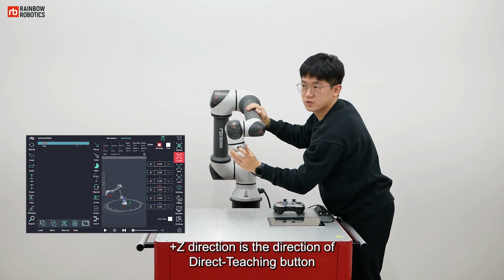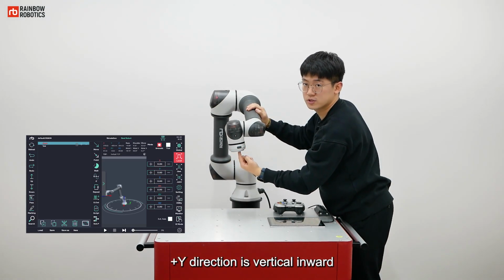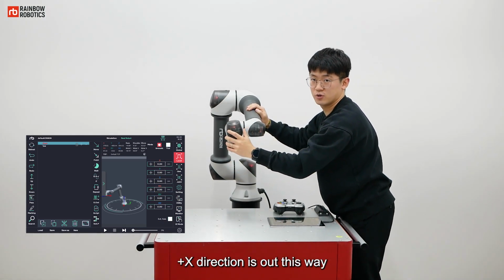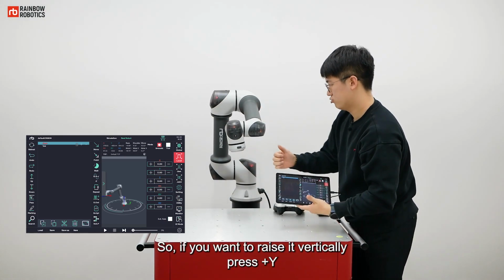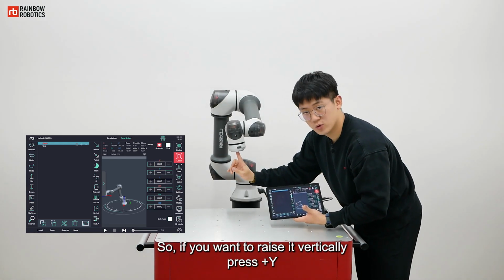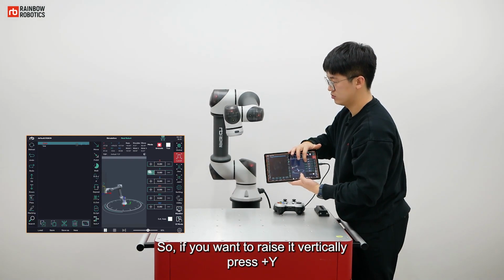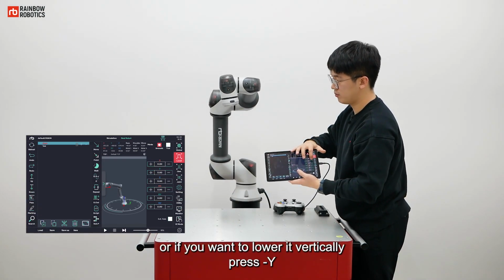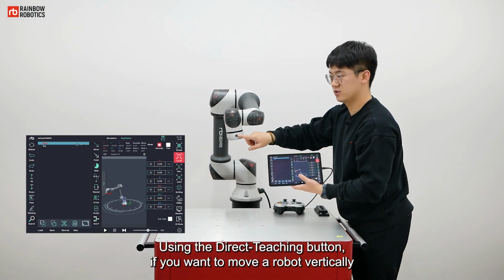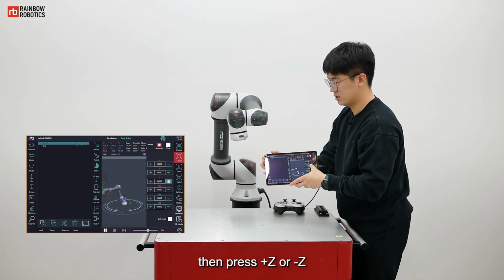Plus Z direction is the direction of the direct teaching button. Plus Y direction is vertical inward. Plus X direction is out this way. So, if you want to raise it vertically, press plus Y. Or if you want to lower it vertically, press minus Y. Using the direct teaching button, if you want to move a robot vertically, then press plus Z or minus Z.